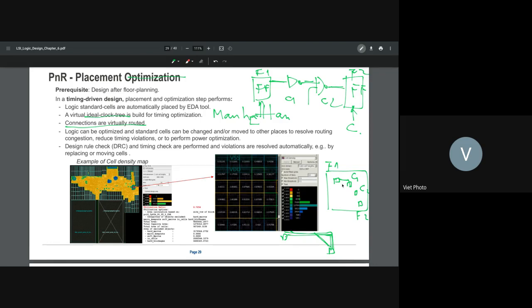When they can calculate that, they know the timing through this part, and they can see whether it meets the target or not. If it meets it, it's okay. If not, they have to move this one around. Oh, now it's too far away, so I have to move this one up here, and along the way these two will move up. So in placement there are two steps. One, the pre-placement with the rough calculation, where they put in a seed, meaning they place randomly at the beginning, and then from there they calculate and readjust.